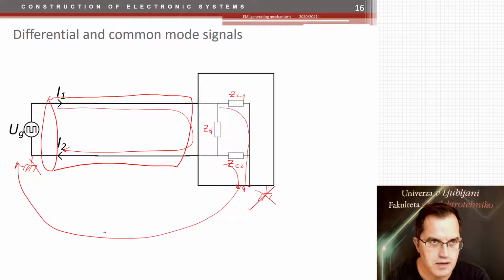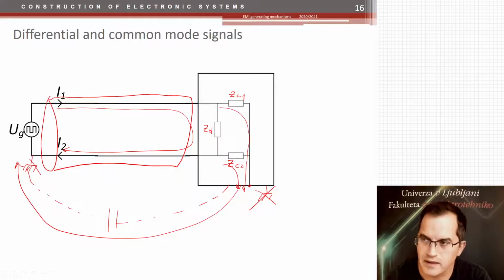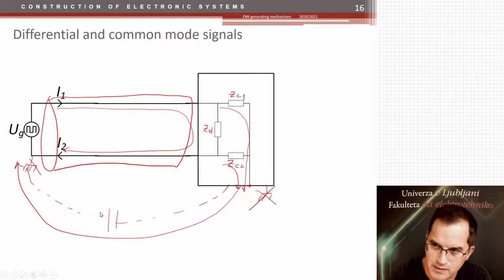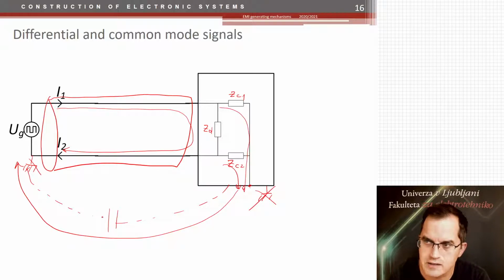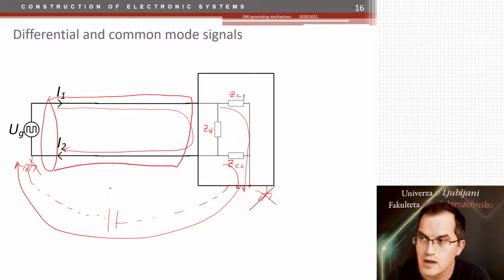Then this connection can actually be made through the air. Here we can have a big capacitor, which is represented by the space around. I said big capacitor, but actually the capacitance is very small, though dimensionally it can represent the whole room. So there is a capacitance path present through the air, and this return current can escape through that as well if it contains high frequencies.